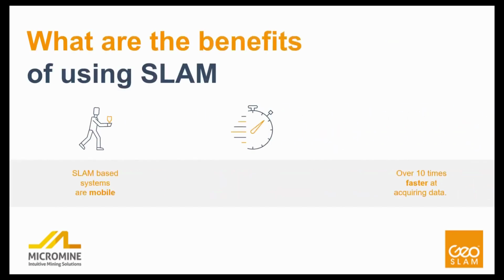There's some massive benefits to using SLAM. So obviously the system is completely mobile. You literally hold it in your hand, or you can put it on top of your vehicle, and you just capture as you move through the area. As you move through that whole area, it'll create a very, very accurate and dense point cloud of that area, which I'll show in the next slide now.